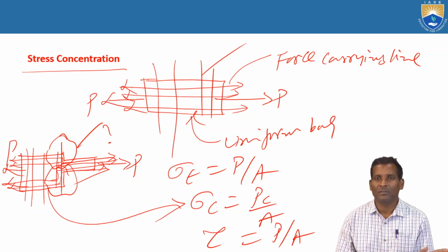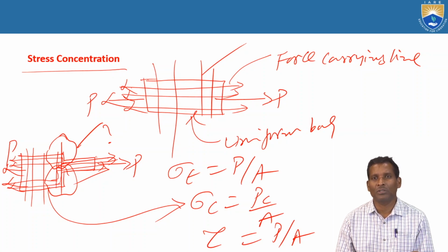You reduce it by creating notches and fillets, and always avoid sharp corners.